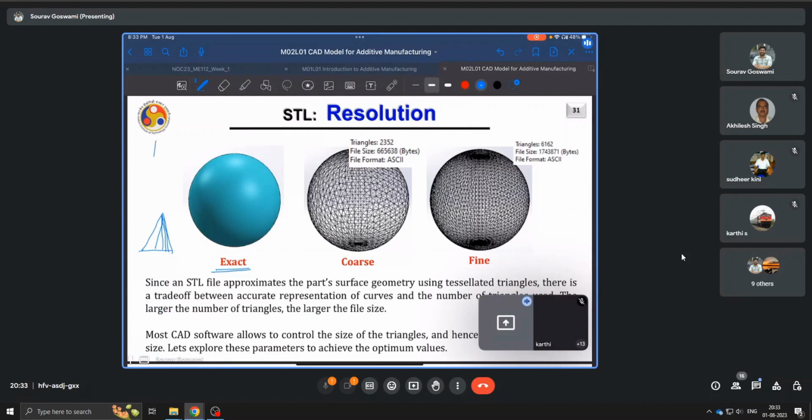So you have a triangle with a very high aspect ratio. And after a point, it becomes impossible to distinguish the two edges because this one has grown so small. So aspect ratio of the triangles plays a key role in your computational efficiency as well as accuracy. In certain cases, you might not achieve convergence at all.